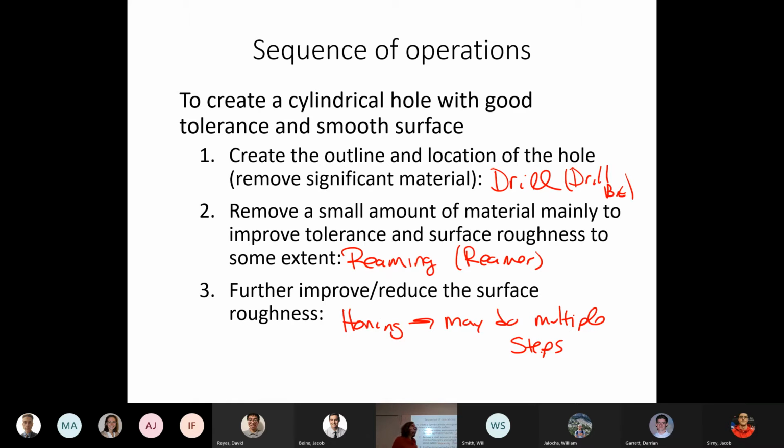We attached the sleeve to the shaft in a process known as brazing, which we will talk about in a moment. But we needed really good surfaces in order to get good bonding. So we would hone the inside of our sleeves.